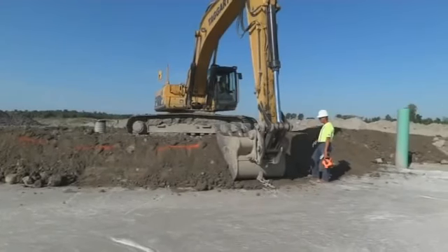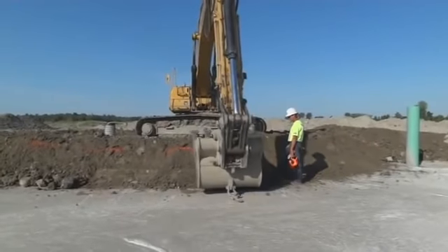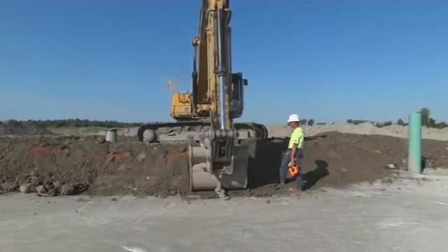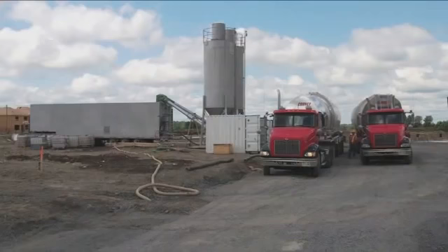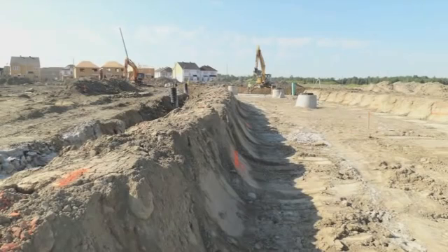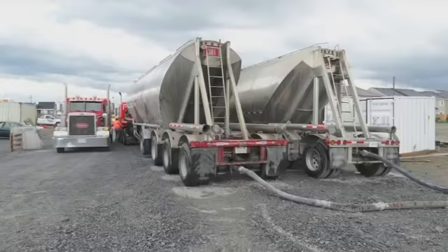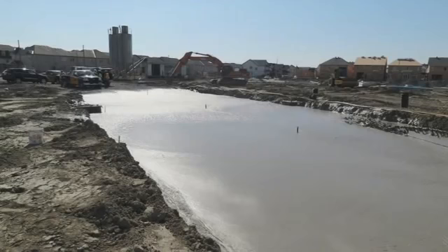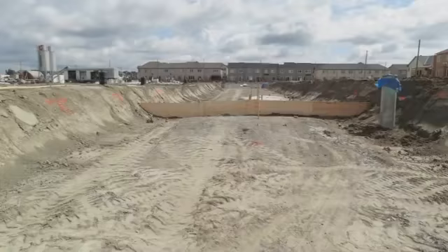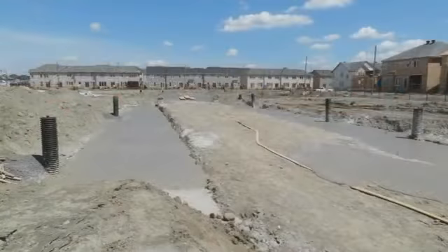Cellular concrete possesses liquid consistency, and the roughness of the soil surface is not of great importance. The depth of the ditch is immensely reduced. Cellular concrete protects the foundation from softening in rainy weather. Calculations by the Canadian company Cemetrix show that the thickness, depth of the road base can be reduced 5 times in case cellular concrete is applied instead of traditional gravel.